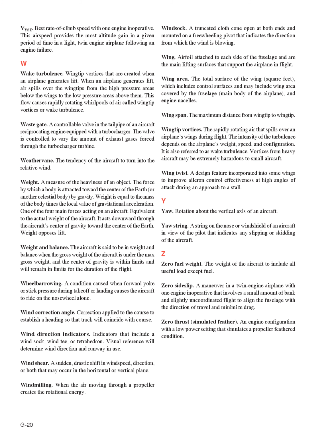Wing twist. A design feature incorporated into some wings to improve aileron control effectiveness at high angles of attack during an approach to a stall. Yaw. Rotation about the vertical axis of an aircraft. Yaw string. A string on the nose or windshield of an aircraft in view of the pilot that indicates any slipping or skidding of the aircraft.